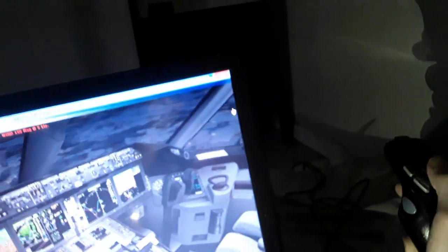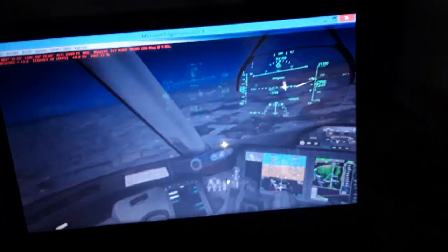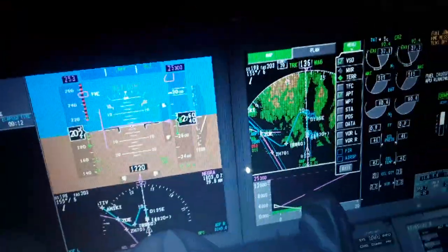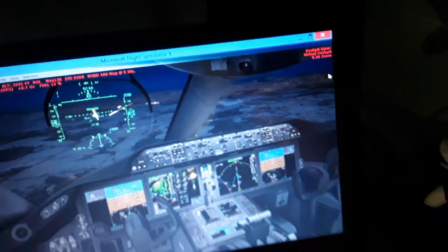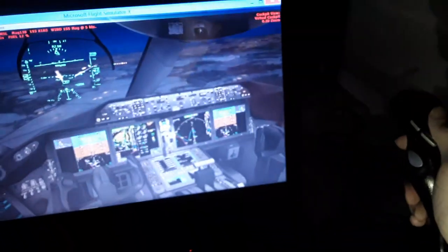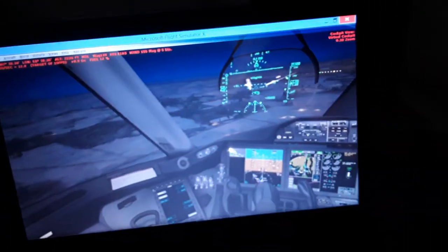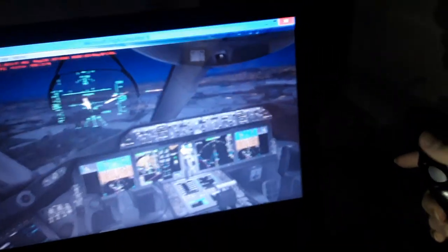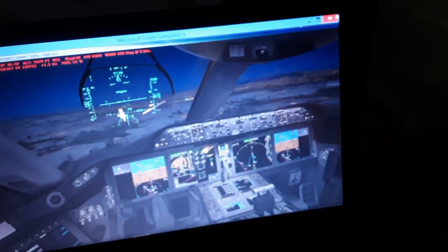Use a little bit more flaps over here. Also a little bit more engine power, and we have also the LSZH localizer here. You can be aligned with the LSZH localizer anytime we need. We have a little bit of sideways wind over here, the crosswind and some wing gusts. So we need to use a little bit more flight controls for alignment with the crosswind component over here.